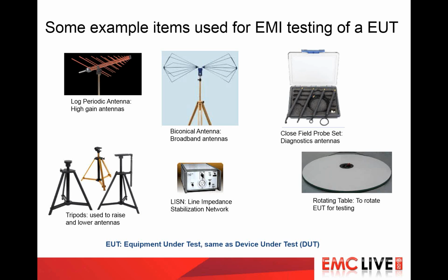One thing I always try to remind everyone, when you take your device in to be tested, or when you're doing your design of your device, if you're using house power, be sure to use as short a power cord as possible, because a long power cord is an antenna, and that's going to cause you problems. I've talked to people that have had failures, these were conducted failures, and they had to shorten up the AC plug-in cord, to make it shorter so it wouldn't pick up noise and cause them to have failures that way. So always use as short a power cord as possible.